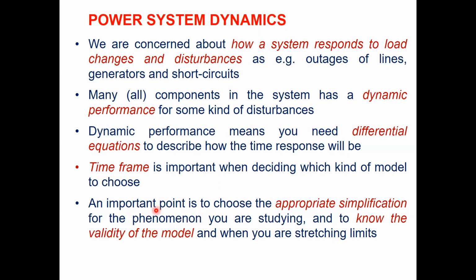As I said, let's say you want to study the fault. Then for the fault analysis, the generator model has to be a detailed one, and the transformer model has to be more detailed too, because the fault current will flow from the generator to the transformer. The saturation part is very important, in how well you are able to model the saturation effect of a transformer.